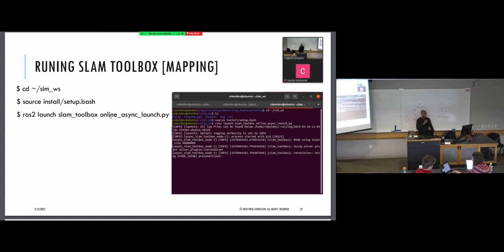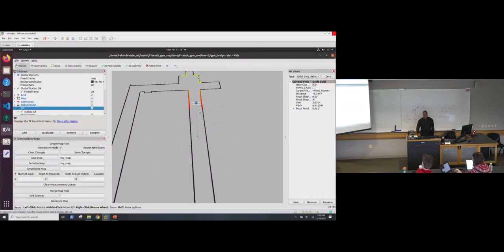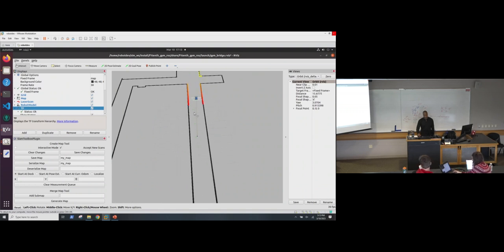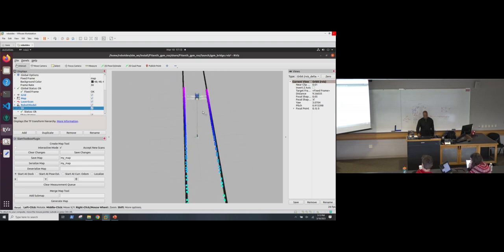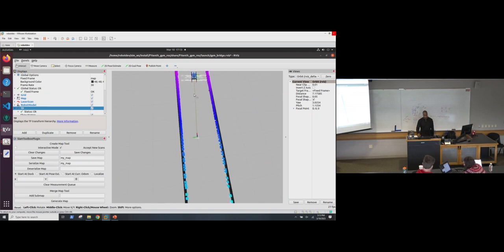Yeah, it could. The reason why I say that is going back to here. The simulators are great, but they also have a problem. You can see here, these laser scans are almost perfect in this picture. But on the real robot, it's not going to be that. It's going to get false readings all the way in here, and especially the faster you move it, the more bad results you'll get. In the simulation, I can run this at real speed at the same time and wouldn't have any problems with that. But you want to have a lot more noise.